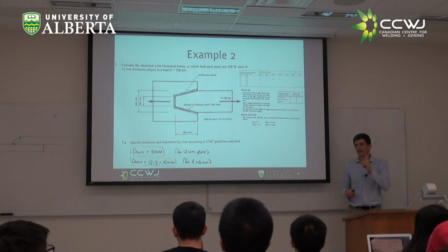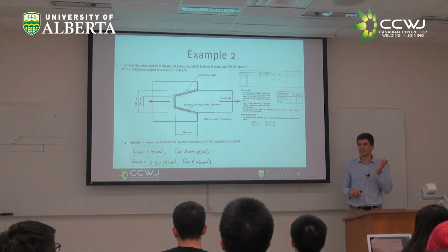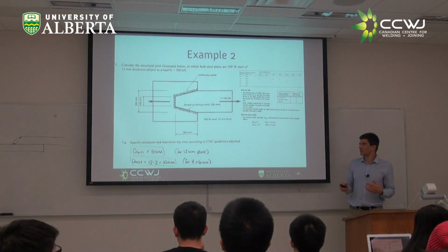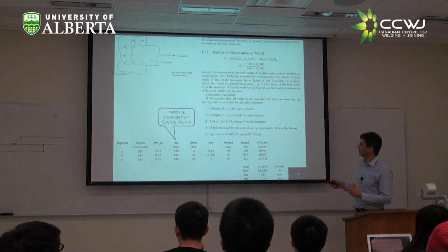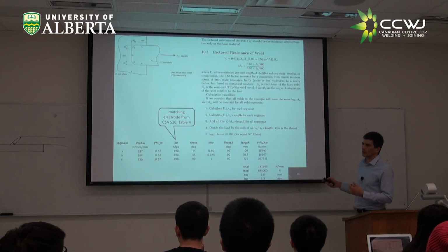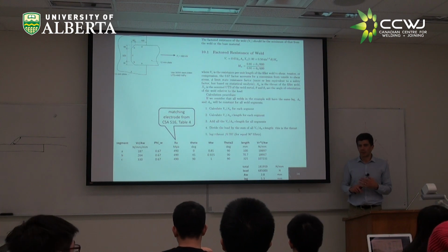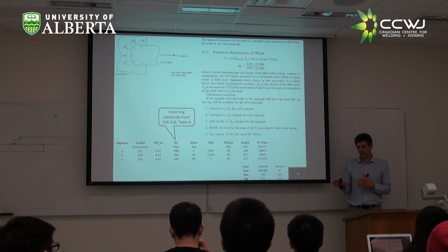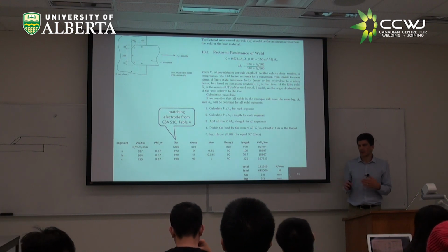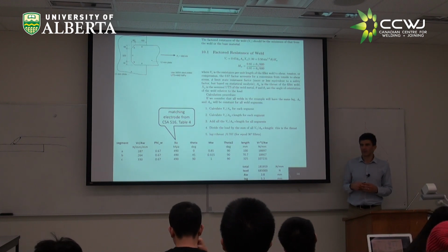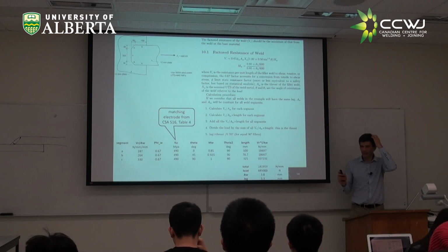We're doing simple square fillets, but we can have a crazy fillet that would have a much more complicated way of calculating that square root of 2 factor there. No problem. We can calculate it with the same formula. We can calculate things in which we have forces and fillets that are transverse, longitudinal. Very powerful. Questions or comments?